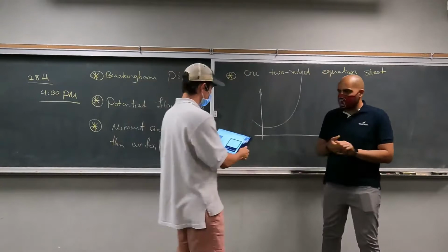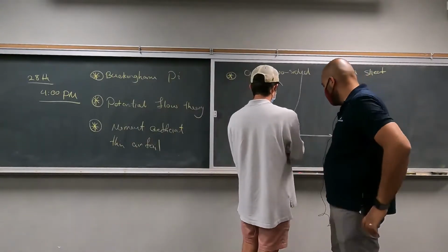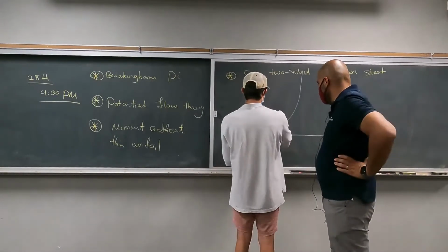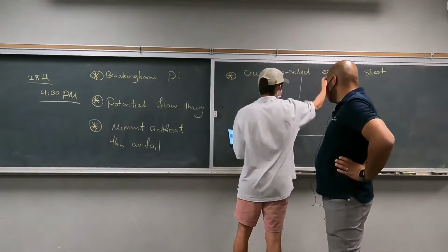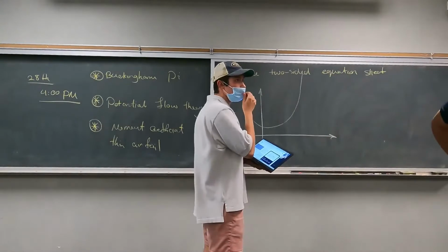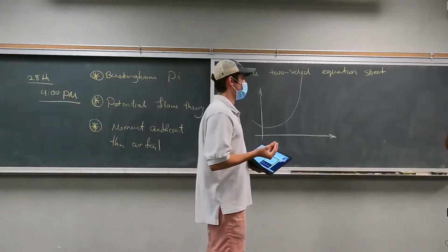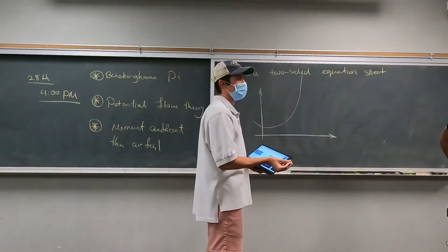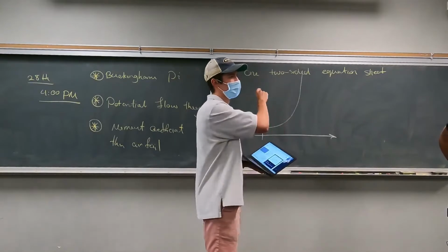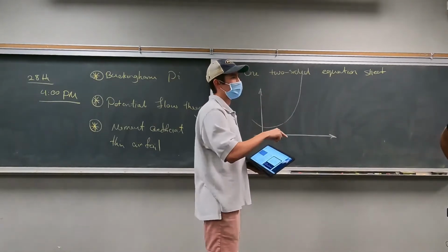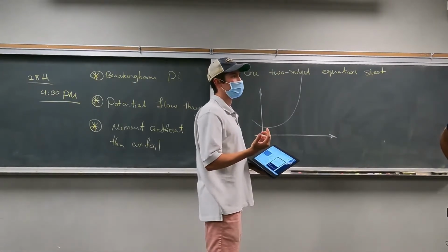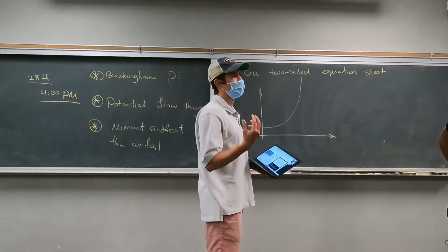I was wondering if there's a thin airfoil theory for coefficient of drag versus angle of attack, where normally it does this and theirs did something like that. Are you asking whether there's an analytical solution for it? There's an ideal CL versus alpha, thin airfoil theory, but that's not necessarily the ideal. Thin symmetrical airfoils are not going to give you the best lift, as in the most generalized, most idealized conditions. I can't really think of the best.